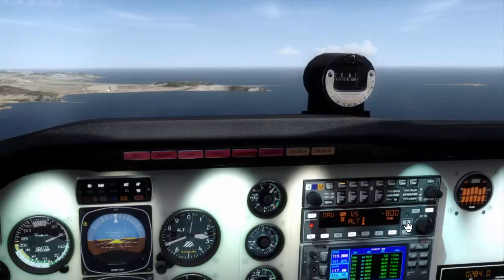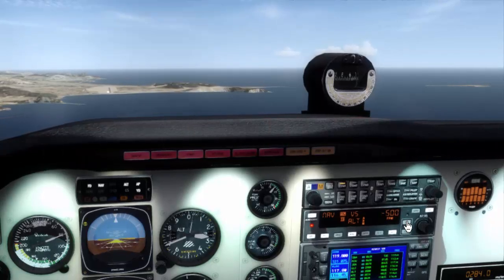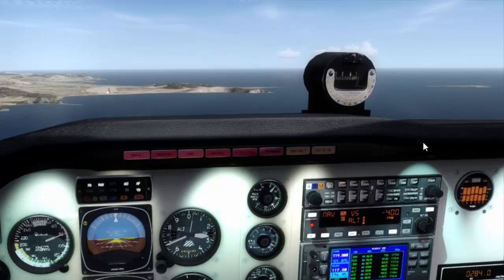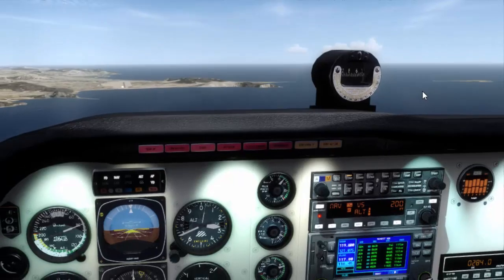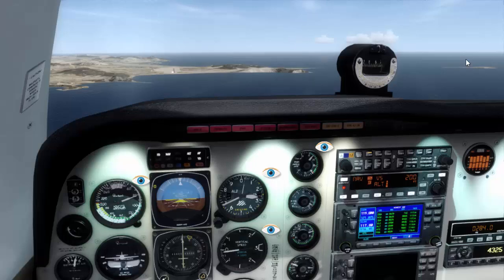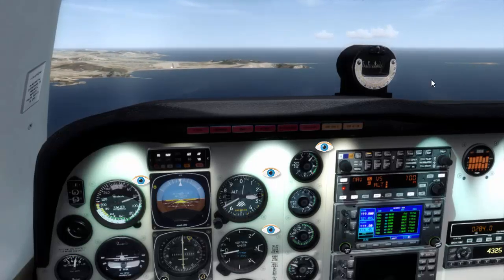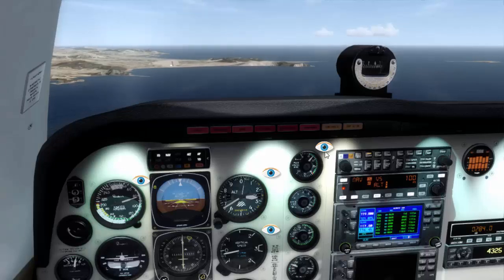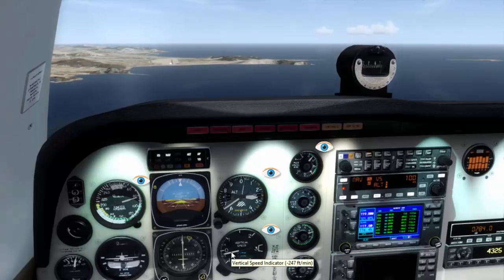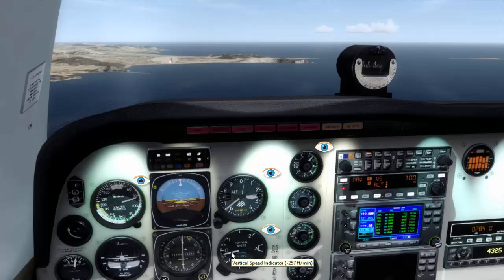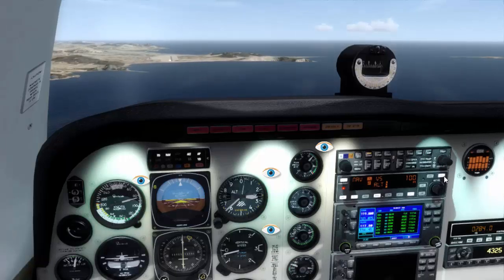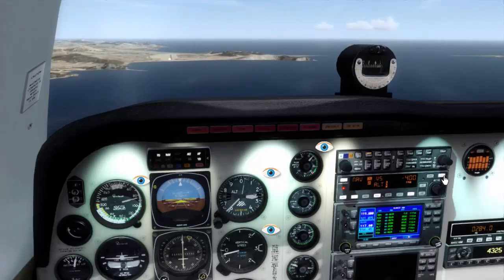I will tell the aircraft to descend to 200 feet, that is almost touching the water, and I will program a descent rate, as we have seen before, of 400 feet per minute, and I am showing you with the eyes all the gauges. You need to take a look at the variometer to see we are reaching that particular descent rate. You need to take a look at the altimeter to see that effectively we are descending.